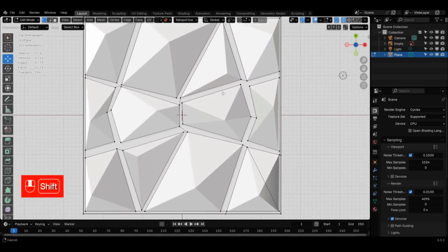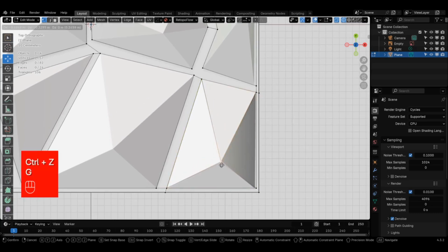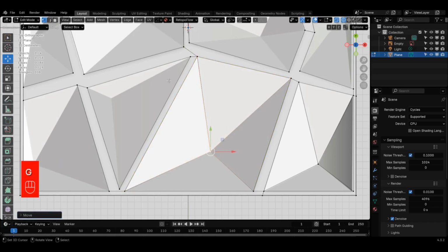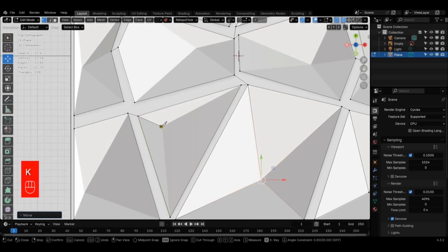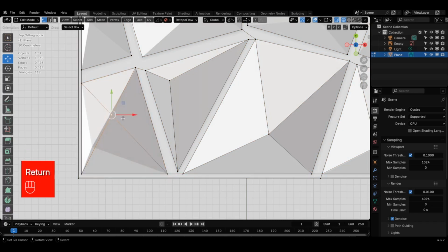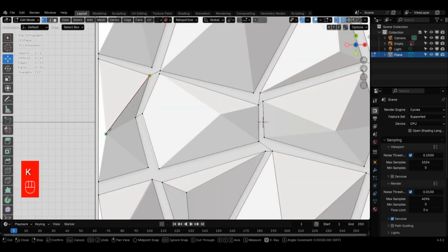Now that we've established the main contour of the shapes, it's time to go inside and add some internal support cuts. We're using the knife tool again to place these lines. The purpose here is to define the highest point, or the apex, of the panel's form. These cuts act as guides for later steps when we adjust the shape to give it depth and dimension. By placing them now, we ensure the panel will have a crisp, deliberate, and professional-looking curve instead of a soft, unintended roundness.